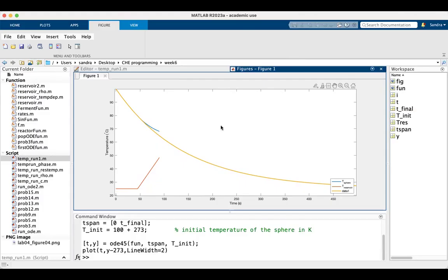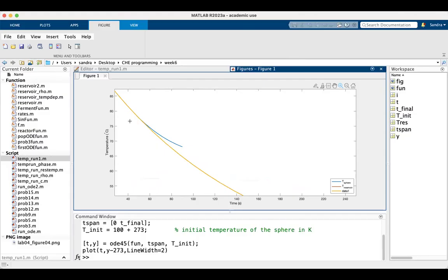Let me just zoom it for you. See, there is a difference in slope. Up to 45, whatever behavior that we observed, that behavior is there. But after 45, you will see the temperature drop. The rate at which the temperature drops has varied because your T reservoir temperature is varied. So this yellow one was the initial system that we observed.